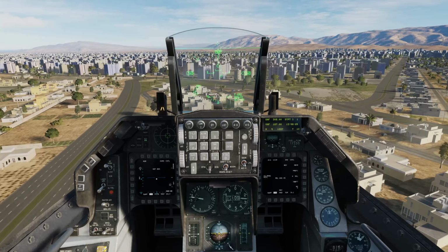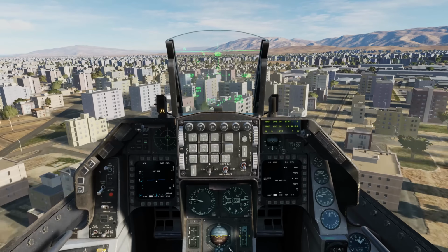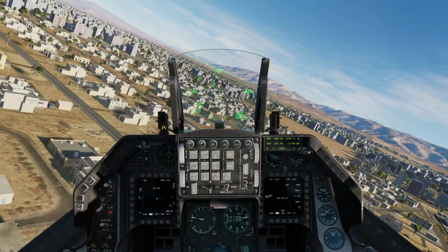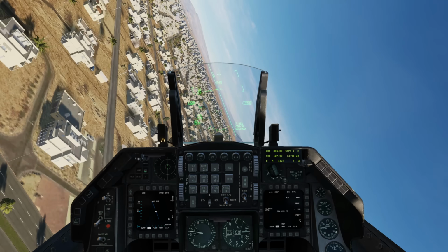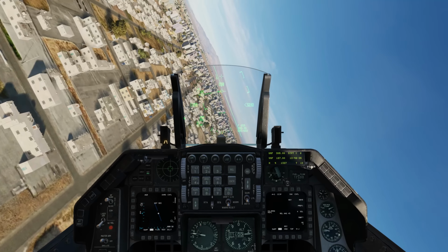If you have a long flight in which you may encounter navigation drift, it's a good idea to have some geographic landmarks along the way to act as fix points to update the location of your steer point accuracy. Let's get started.